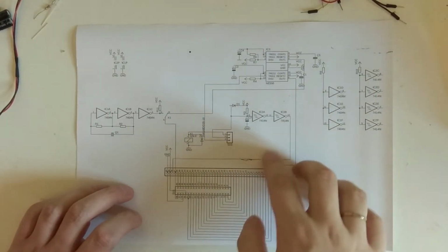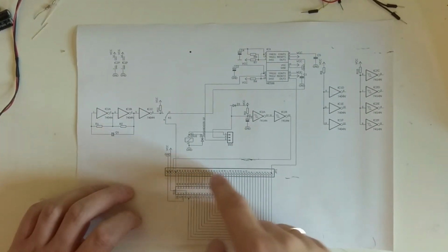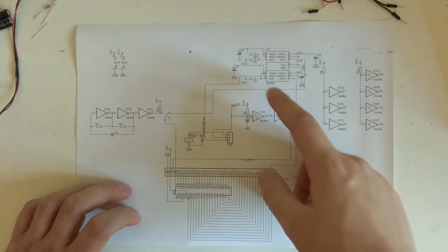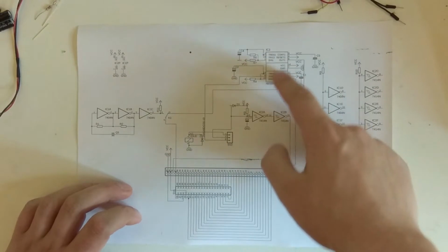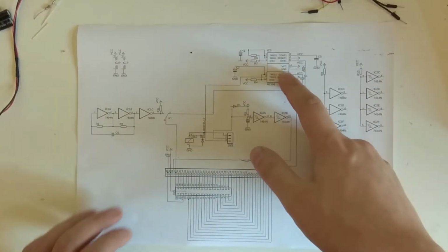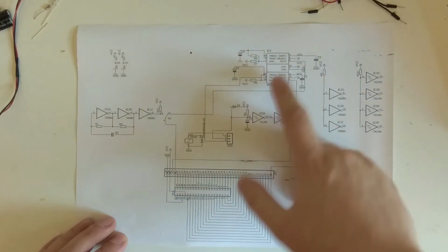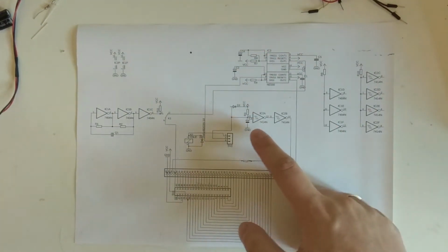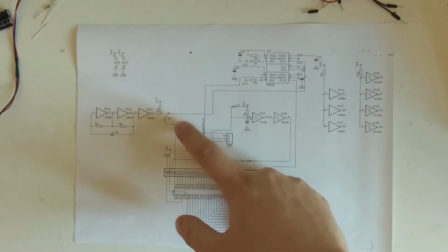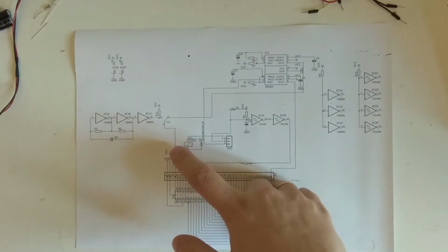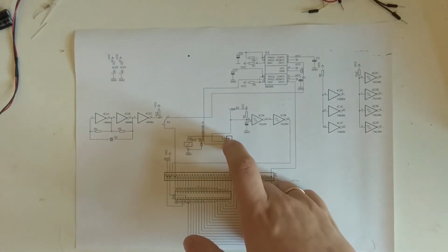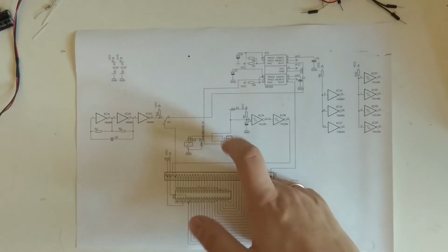And they will put the reset and the clock down here. Instead of a single stepping circuitry, I just have a very slow running clock. This is an NE556, basically a double NE555, with one of them creating a slower clock of about 1 Hertz. It's just going off to a relay, and that relay is switched over this connector, which also provides the switch for the manual reset.